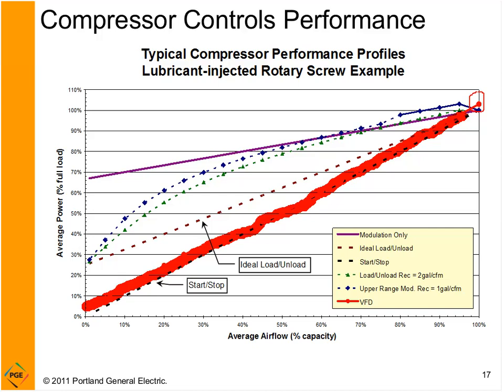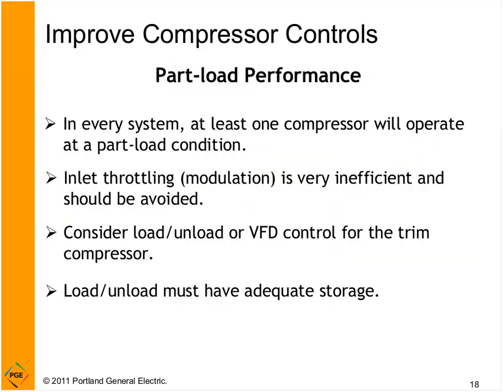So you might ask yourself, gee, should I buy a variable frequency drive compressor and operate it at full load? Well, no, for two reasons. One, it's less efficient. Secondly, why would you pay an extra $10,000, $20,000 for a variable frequency drive if you're just going to base load it, operate at full load? That would be kind of pointless. So I think you can see that. But anything below about 95% of full load, and you're in the money. And you can clearly see the differences in the benefits.